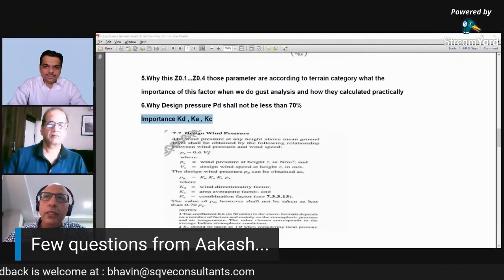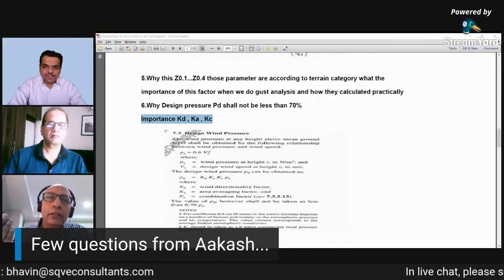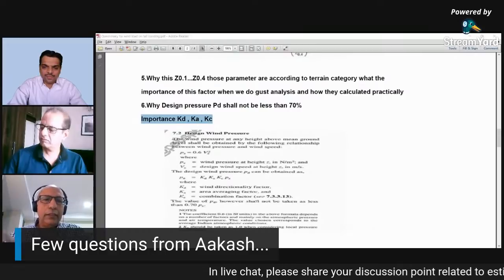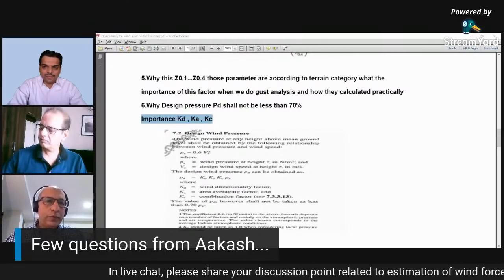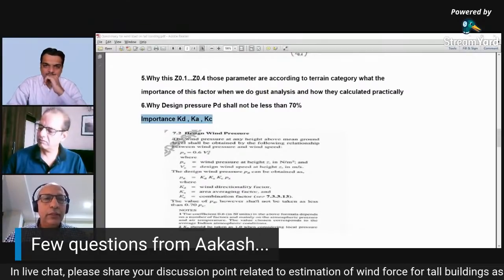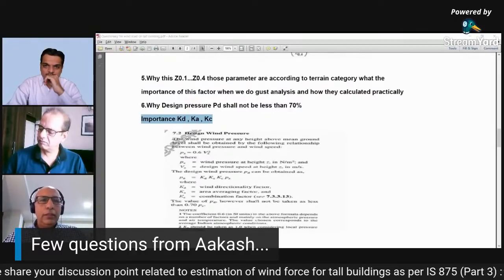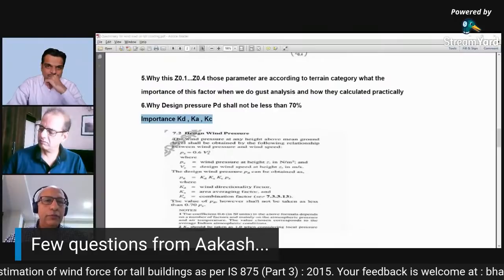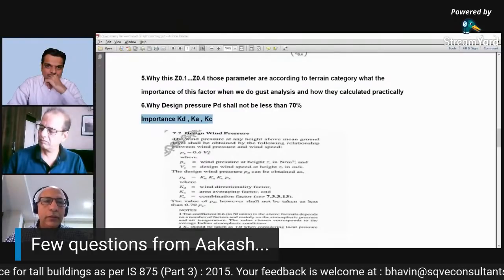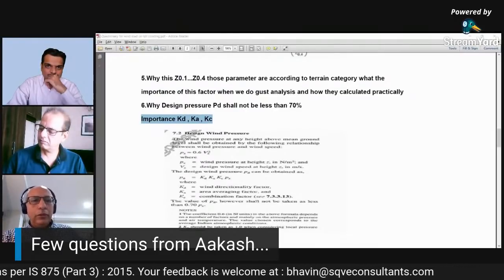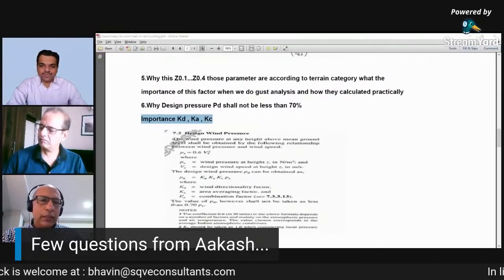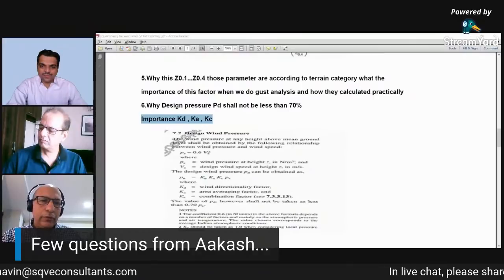If you are looking at a structural member that supports a very large section of a roof of a warehouse, with a tributary area of, say, 50 square meters, this large member will not be affected by a small vortex at the leading edge of the roof.